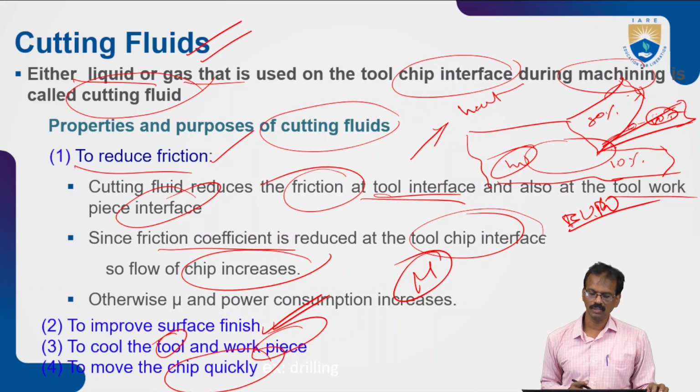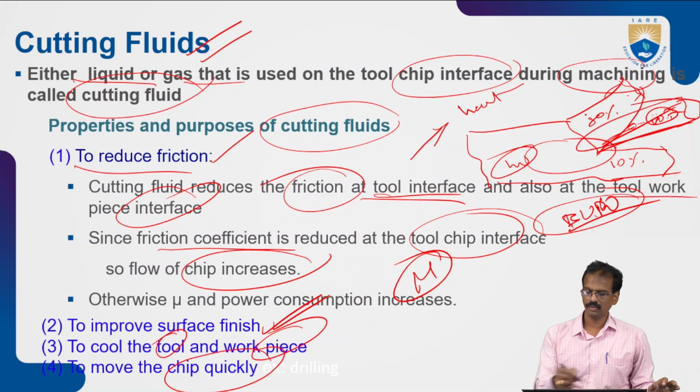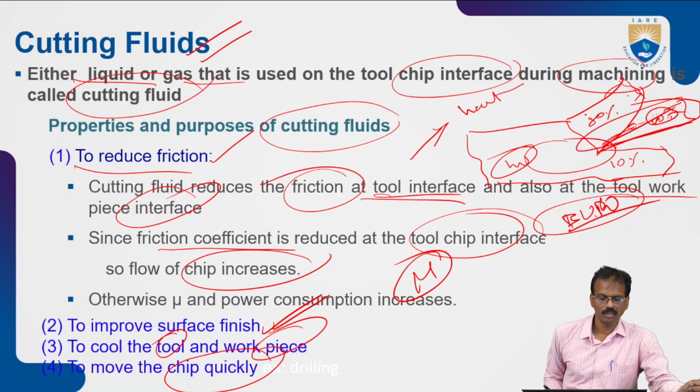and tool. Next, to reduce the frictional coefficient or friction between the interface of the tool bit and workpiece. Next, to overcome the built-up edges on the tool bit. So these are the main advantages of the applications of cutting fluids.